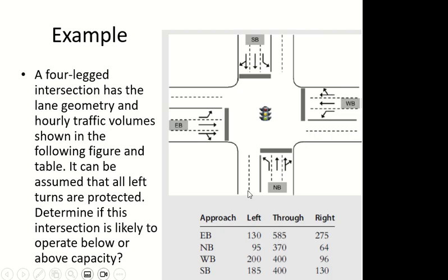So this will be one pair. The other pair will be the opposite: left turning of the eastbound and straight and right of the westbound. The straight is also called through, so keep this in mind. So we have two pairs, one with each left turning, and the same for north and south as well.